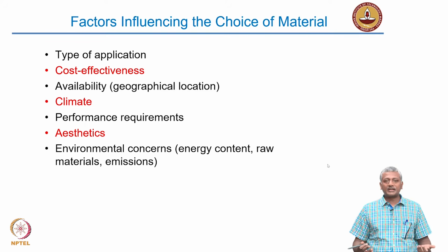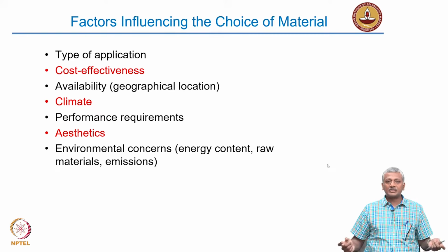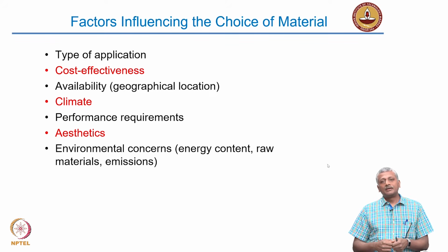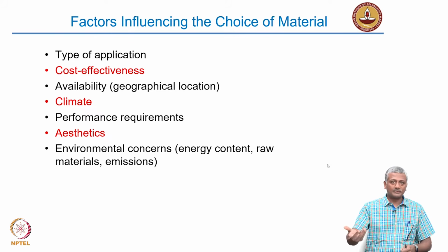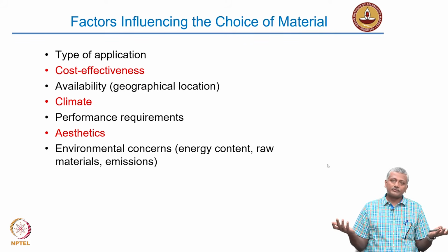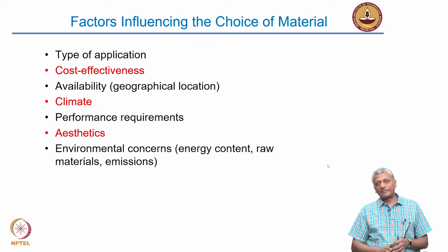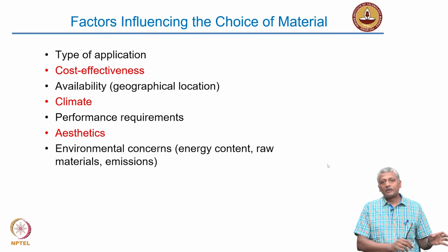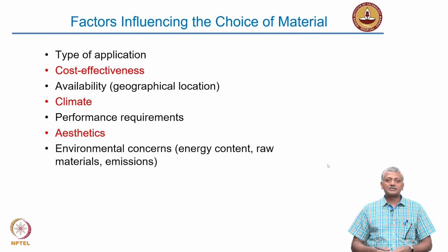So, it can actually function for an extremely long period of time, but however, in modern structures, we employ concrete in connection with steel reinforcement. And steel obviously has a tendency to corrode. You can't stop that. It will corrode eventually. Okay? So, you can only design a structure for as long as it takes for the steel to corrode. If you design a structure with plain concrete, it may last for a very long time, just like your stone and lime did. Okay? So, there is no problem with that. However, when we start using steel, the service life of the structure is shortened because of the time to corrosion of the steel.